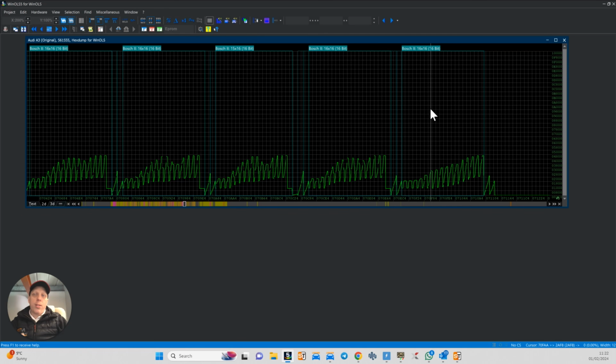So it's not a case of changing every single map either. It's understanding what does what, how it does it, what have I got to do to raise it, and how far can I raise it. You're going to have sensors, because the way the ECUs work is they have a bunch of sensors on the engine which feed back to the ECU. So you can have a rail pressure sensor which tells the ECU what rail pressure you're at. You've got boost pressure sensors, map sensors that tell the ECU what pressure you're seeing, and it uses those sensors to adjust based on the tune.